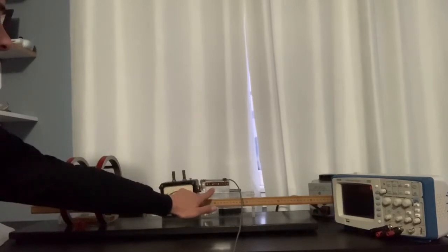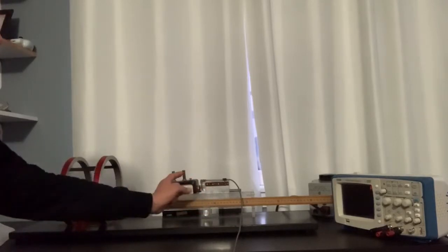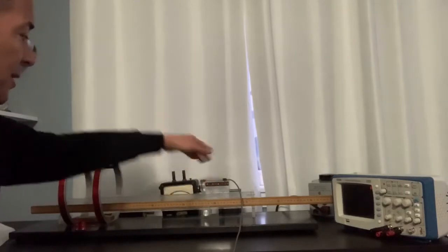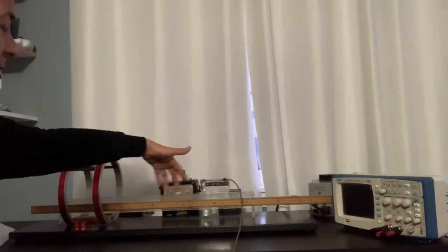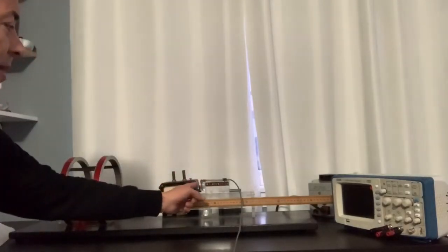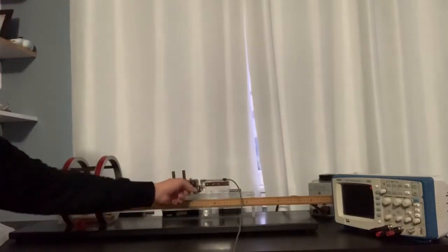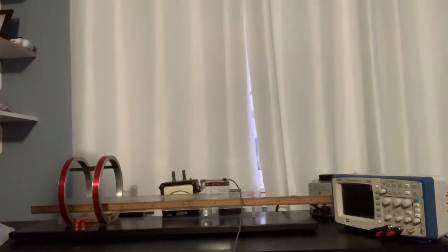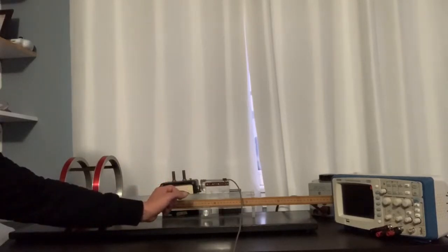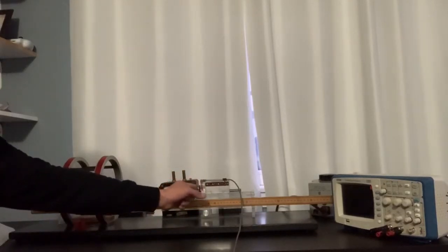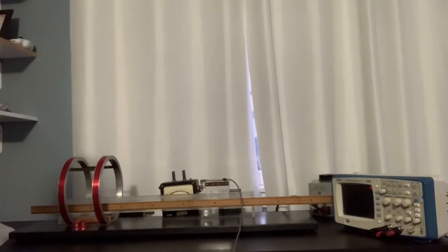Likewise, we have this search coil here, and the magnetic field in this region that is varying over time will induce an EMF in these coils. And we'll use Faraday's law of induction to calculate the field at this particular region based on the measurements we take from the current passing through those coils.